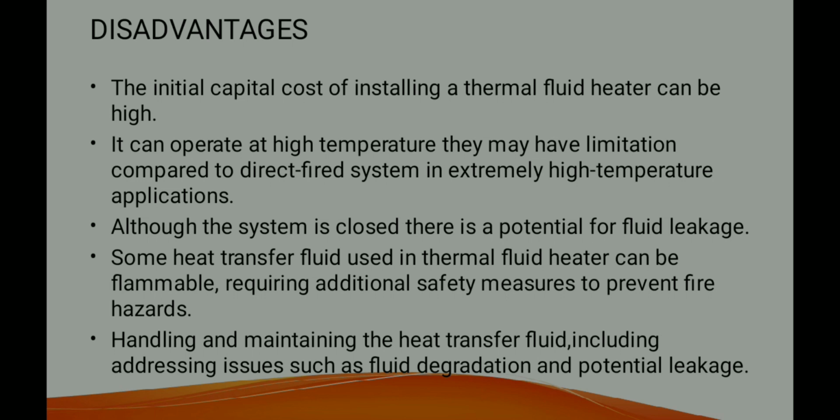Some heat transfer fluids used in the thermal fluid heater can be flammable, requiring additional safety measures to prevent fire hazards. As we know, in a system working as a closed system, the fluid is reused. It goes to the different heat exchangers, and again it comes back to the thermal fluid heater. It may have a chance of being flammable. Additional safety measures to prevent fire hazards are necessary for a thermal fluid heater working in a larger system.